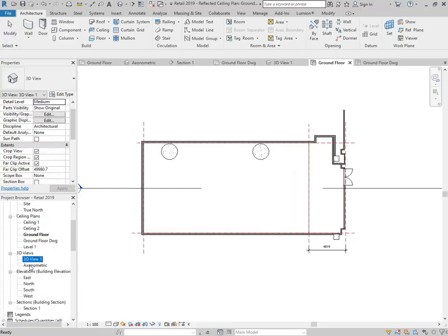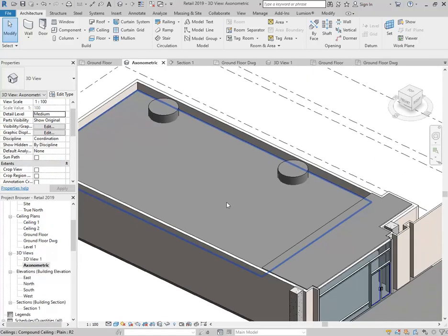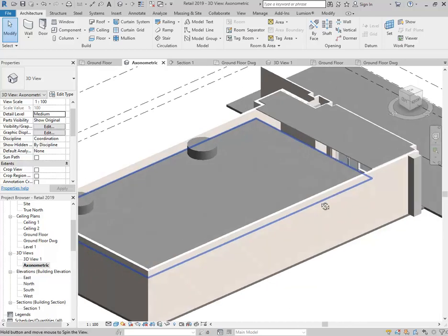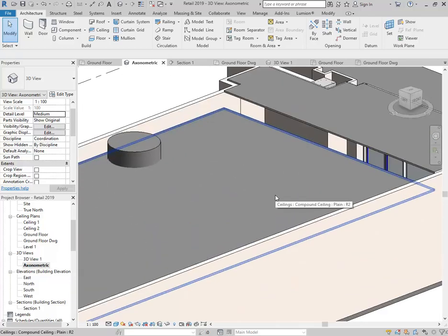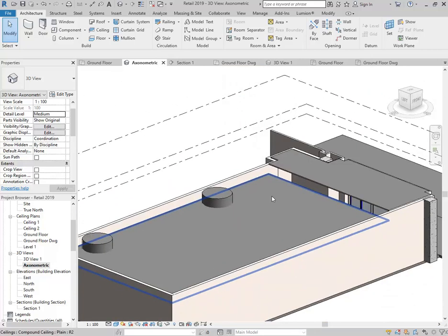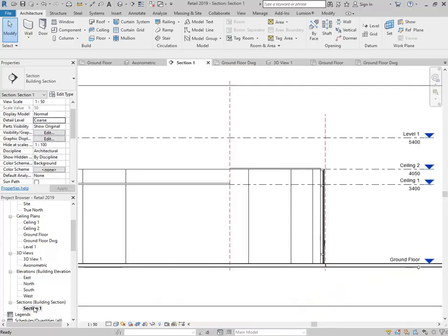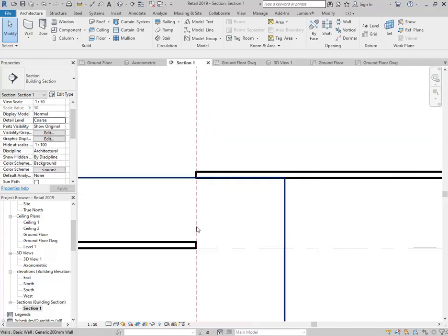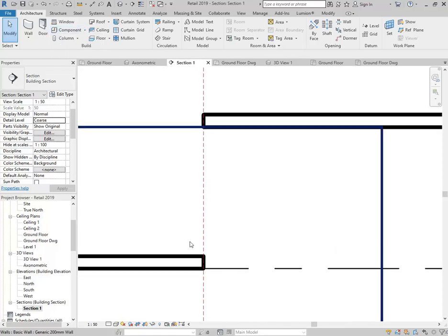And again, if you can do that, that means the ceiling is visible in the view. Now, we've got a problem though, because if we look in the axonometric view, you're going to see that there's a gap. We don't want that. Right, so there are a few options there. You could build a wall or model in manually using some of the modelling tools that you have with Model in Place. You could model that extra part of the ceiling in there, which really functions like a wall.